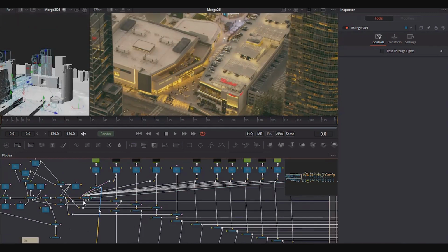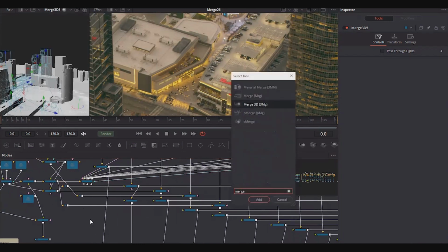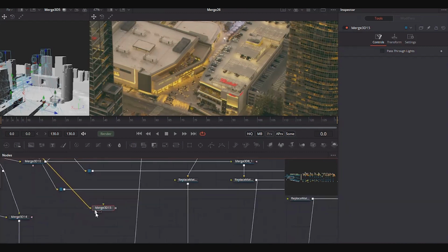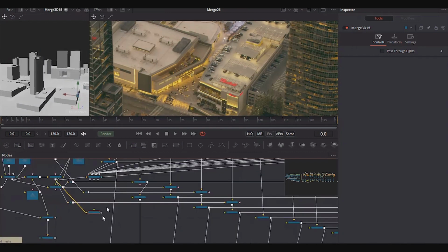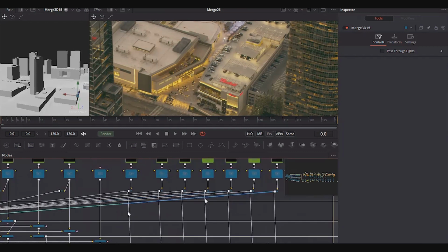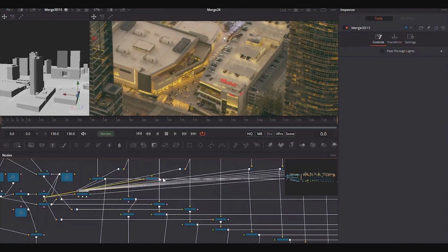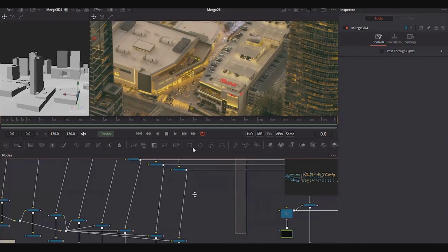What you can also do is, if this is getting a little bit too busy and chaotic, you can create a new 3D merge, pull this in, and then bring your camera into just this one by itself so that you can get your alignment and really check where it is against the surface of something. You don't need to have all of these cameras plugged in here. I just didn't remove them as I went. If you wanted to have a unique merge below each camera so that you can check the exact positioning, that's also fine. This is more just for helping you line things up.